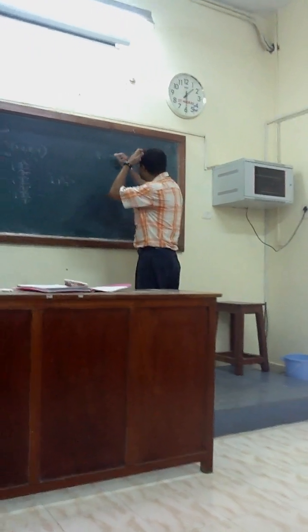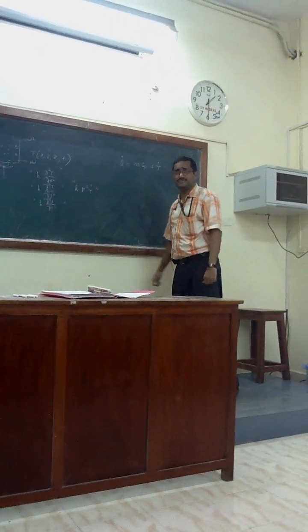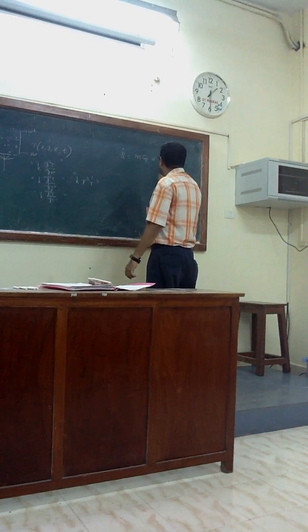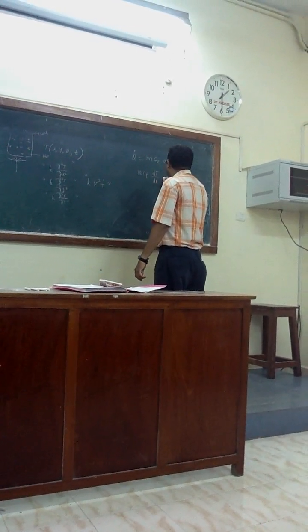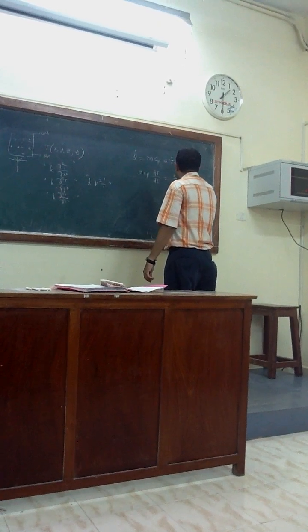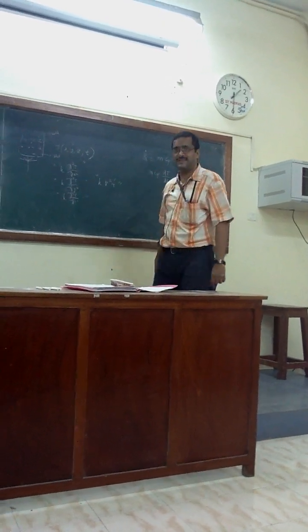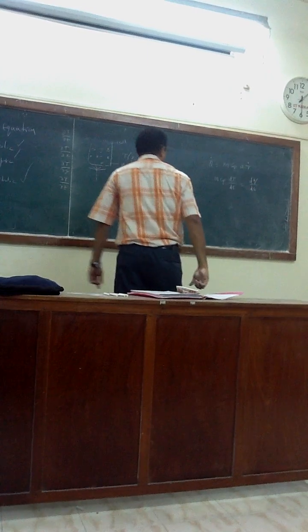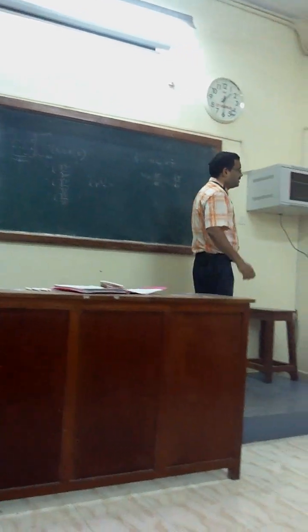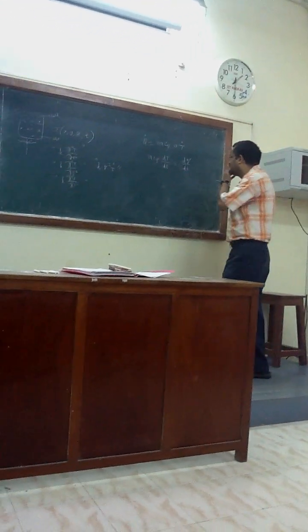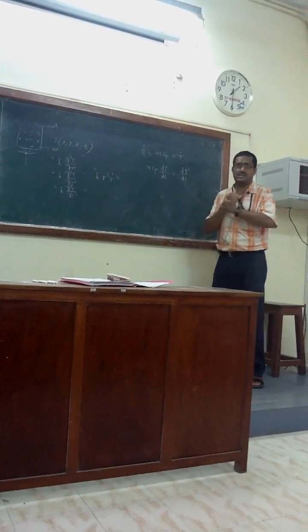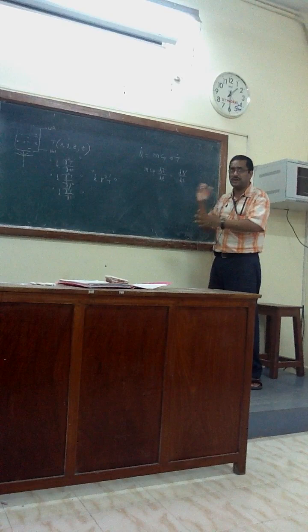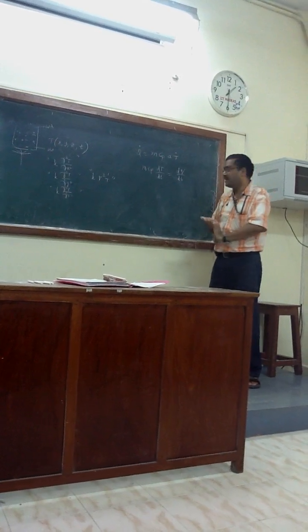Sometimes we talk about rate. So what actually happens, it is m Cp dT by dt, which is dQ by dt. This is the heat supply. This equation is actually assuming that there is no system resistance, everywhere the same temperature.